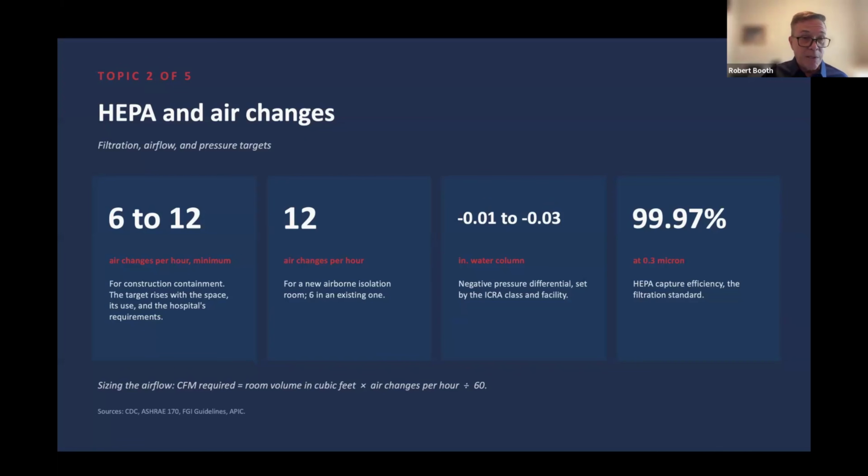If you're doing asbestos, we want you to follow those guidelines, which are HEPA filtered respirator and personal protective equipment to remove those. But in the case of common construction debris, we want you to use good industrial practices, and then you wrap it up and you throw it away. Is it biohazardous? No, absolutely not. It can go into the regular trash as long as there's no biohazard contaminants suspected. So, yeah, that's a great question.